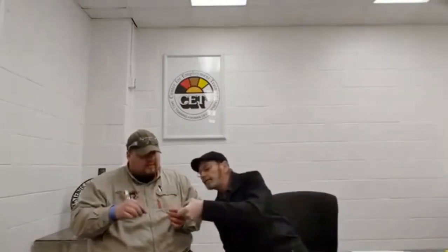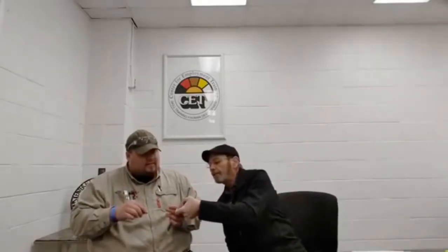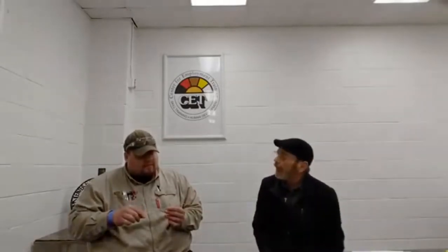But this rod can do stainless steel. Stainless steel? Mm-hmm. Like coupons? Well, no, like just regular stainless steel welding. If you had thick stainless steel plate to weld, you could weld regular thick stainless with that. Right here, this is what we call 308L. Oh, 308. So 308 is going to be our stainless. Okay. So that's the type of stainless steel that you have.